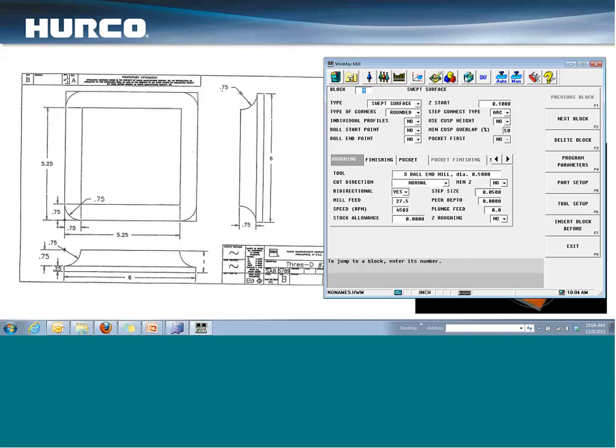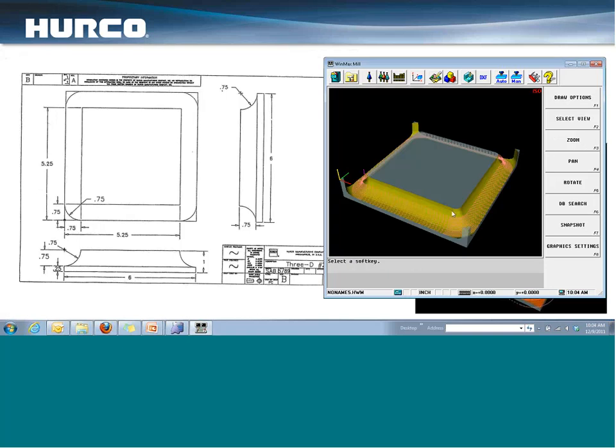And one of the biggest advantages, I think, is now our tool path. You'll notice that when it cut this, it was cutting all the way around. There was no more of cutting just one side and then cutting one radius and going on. It's going to cut the whole thing as one surface. So you get a little smoother tool path out of the swept surface.